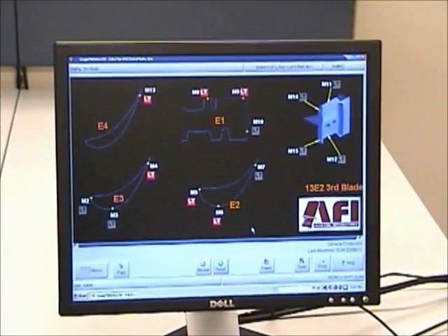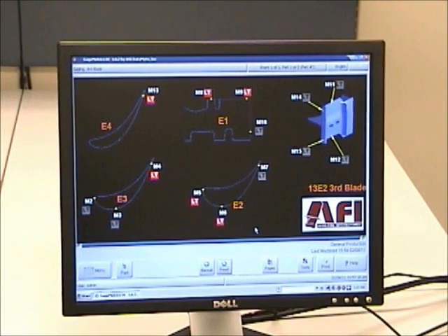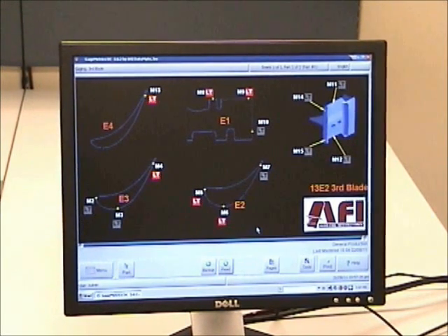The screen that we're defaulted at right now is for gauging. You notice there's an LT, that's gray or red. What that could mean is either a linear travel fault in a minus condition or an over travel position. It means that the probes are not activated in a readable location. In this case, the gauge isn't turned on.